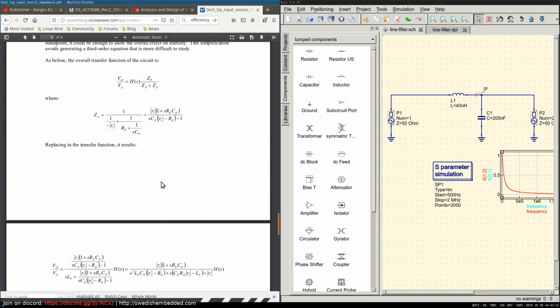Because the interference is referenced to earth, the noise gets into the circuit and affects it, and tries to get out through the chassis and back to earth.